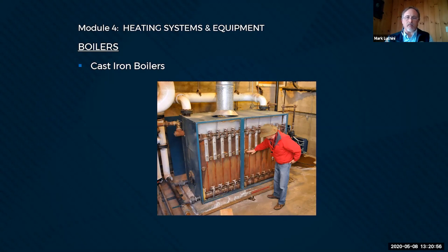Okay, now boilers have gotten much more sophisticated over the years. We have condensing boilers, just like condensing furnaces. They work on the same principle. They'll use a secondary heat exchanger to reduce the flue gas temperature even further and suck more heat out of that flue gas. But they still operate on the same principles and are built essentially the same way as these boilers we just discussed.